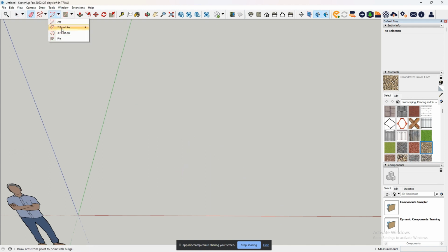Then same thing, I'll quickly, briefly show with the 2-point, which is pretty much the same. The 2-point is slightly different because it is more used for arcs rather than a curved line. So you want to start off with the point, just like the last one. Left is where you want your left side boundary to be, then the right side boundary, and then move it up or down depending on where you want it to be. And just like last time, if it's really blocky and jagged like this, Control plus plus plus, keep going until it's curved.